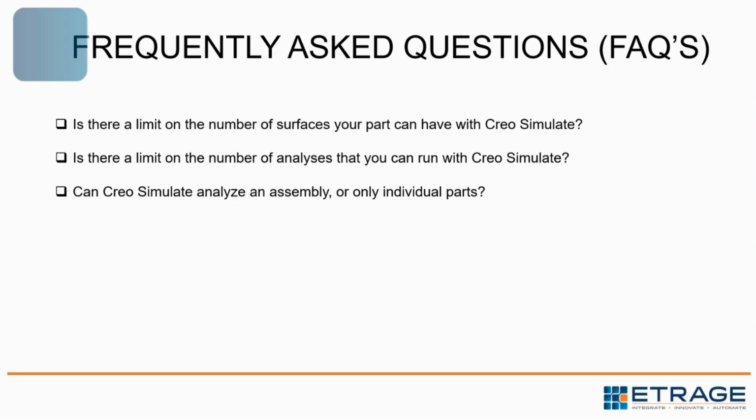Follow-up question of my own on that, talking about RAM requirements and processing speed. Creo Simulate needs far less hardware horsepower compared to something like a CFD tool, correct? Generally speaking, yes. That's because with Simulate, if you're solving an FEA analysis, you generally use a smaller mesh than if you're doing a CFD analysis.